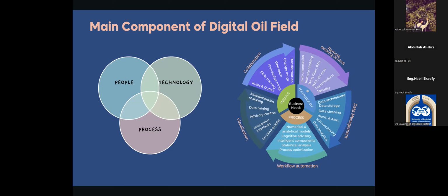This is one rule. The second one: maybe sometimes you are receiving data, but the data is out of tolerance, or below or above a threshold that you set up on your data. For example, your expected wellhead pressure is, let's say, 300 psi, okay? But suddenly you start receiving wellhead pressure of 1,000, or maybe 2,000, or maybe minus 10,000. This means the sensor is not working, the sensor has some issue. So you need to clean that data.